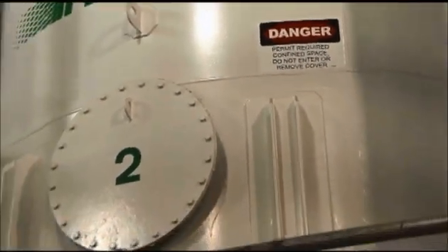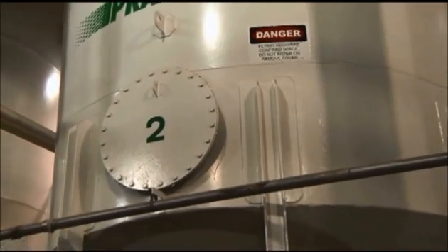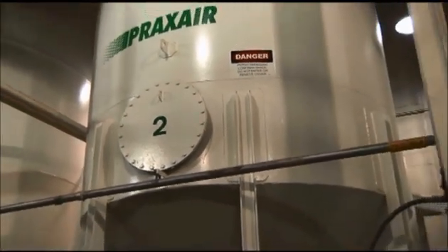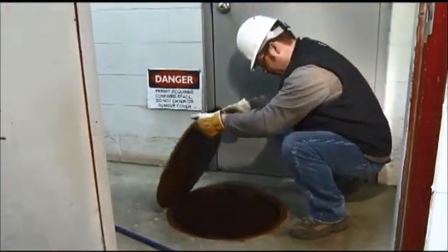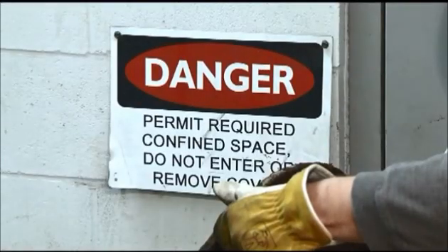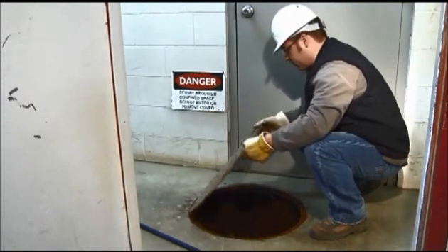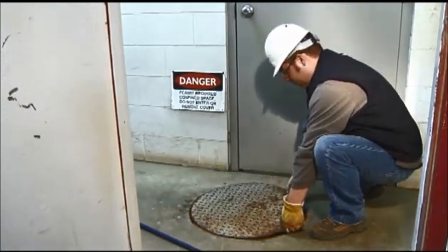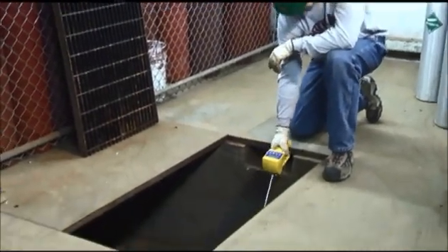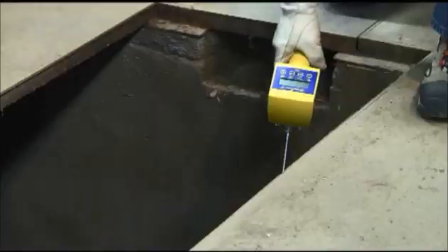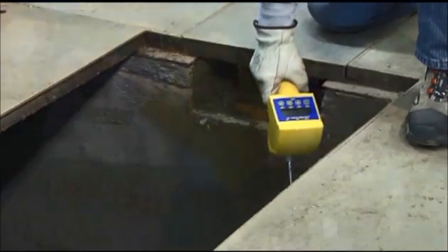Confined spaces come in many forms, and they can be indoors or outdoors, such as the inside of a chemical reactor vessel, a rail car, or a storage tank. Even spaces that are usually considered safe, like sewers, tunnels, or vaults, can be confined spaces. These spaces also have the potential to become oxygen-enriched under the right circumstances.